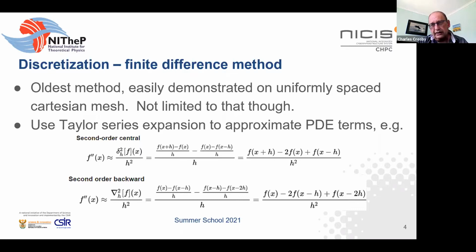But of course, it's not like that. A property that's flowing in from upstream is not going to be the average between what you've got here and what you have upstream. It's going to be dominated by what happens upstream. So it makes sense to bias the scheme towards the upwind side of that particular cell. And that's where upwind differencing schemes come in. So the question is, how far do you take it? You just take the value from next door, which is essentially first order upwind differencing, or do you extrapolate from the two positions upstream, which would be second order differencing?